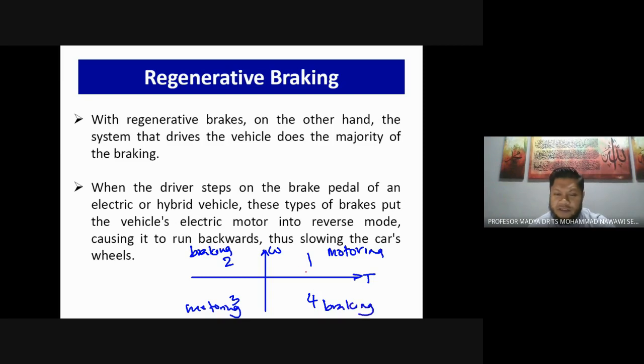And we also have this forward motoring, forward braking. Here we have a reverse motoring, that's reverse braking. So this is omega m, and you also have torque in that direction. And then you can draw for the rest. So you have to look into the quadrants. This is known as the 4 quadrant.